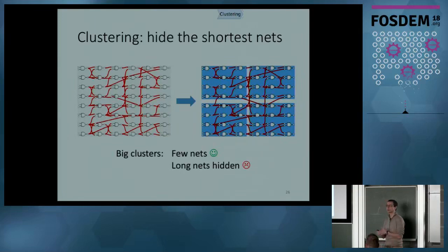And those wires, when going 3D, going through the interconnection for the face-to-face or face-to-back or the vias, etc., they would actually be made longer. So you would lose in performance. So we want to cluster the design so that you can hide all the shorter wires inside the clusters and just highlight the longer wires. So now you have two choices, aside from the clustering method, is to choose the clustering grain, that is the amount of clusters you want in the design.